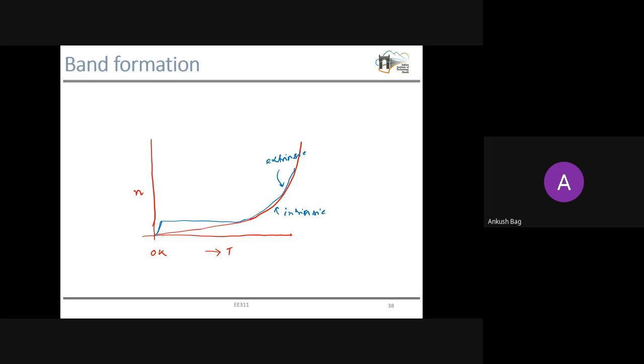Now in case of doped semiconductor, since this dopant level is very close to the conduction band energy, it will donate electrons rapidly. Now after all the donor atoms have donated that fifth electron, the concentration of carriers will remain constant for a certain range of temperature. After a certain temperature, once again the covalent bonds will start breaking. So then it will follow that same intrinsic behavior.